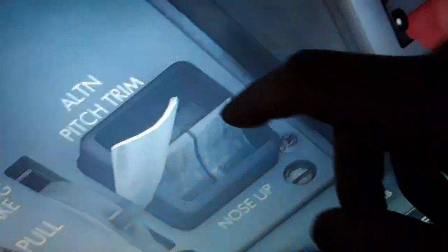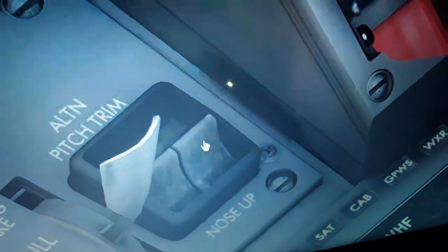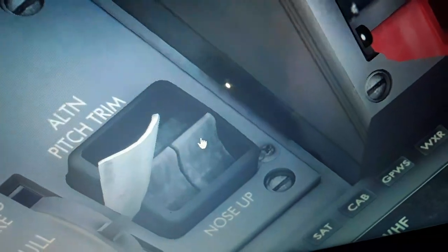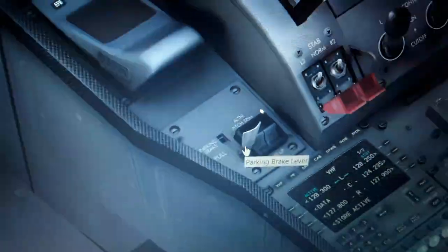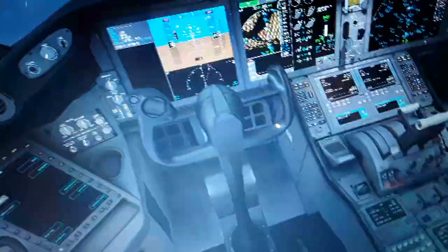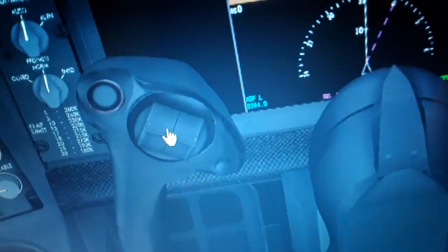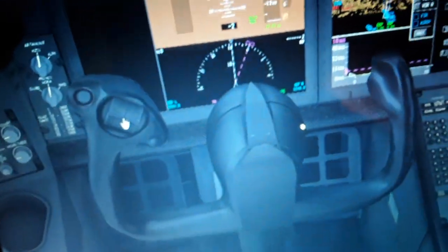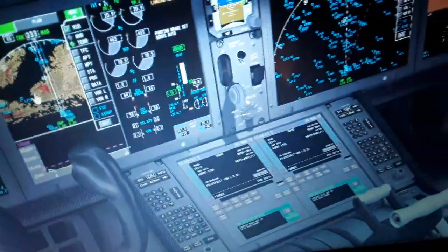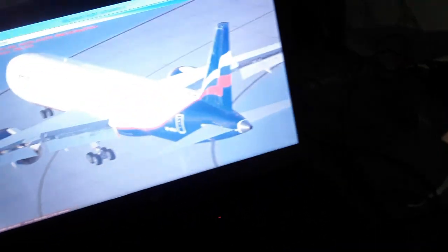So maybe you have no autopilot. You pitch the elevator, the tail of the aircraft, up and down to balance the aircraft, to relieve the air pressures, and also pitch the nose up and down as you fly. So you have the stabilizer manual trim here all the time. You see the elevator trim up and down. We have one more view left over here before going to flight.